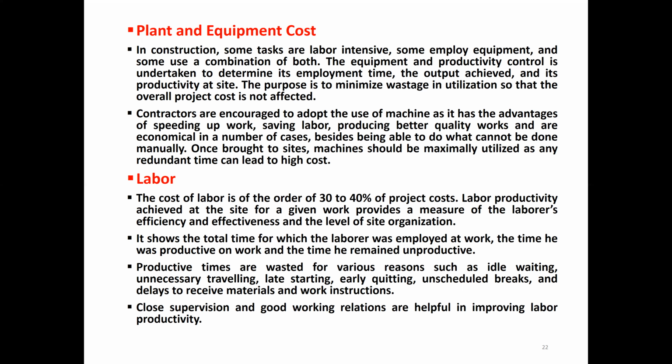Now, regarding the labor, the cost of labor is of the order of 30 to 40% of the project cost. Labor productivity achieved at site for a given work provides a measure of the laborer's efficiency and effectiveness and the level of site organization. It shows the total time for which the laborer was employed at work, the time he was productive on work, and the time he remained unproductive.